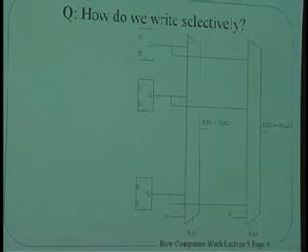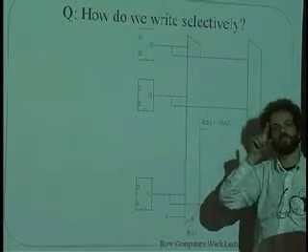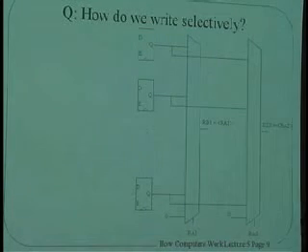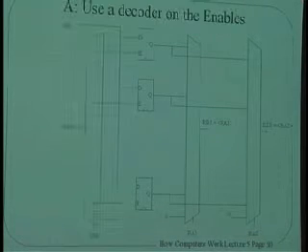In other words, I could gate the clocks. I could put a bunch of AND gates with the clocks, saying depending on which of the registers I wanted to write, I'm either going to trigger this clock or trigger this clock or trigger this clock. Change which shutter gets the finger to press on it. But it turns out, and we'll see reasons later for why this is true, that trying to gate clocks, trying to control which shutter is pressed, is actually very hard to do. And it's actually easier, and you get much more time to get the job done, to disable certain of the cameras and only enable one of them so that all the shutters are pressed at the same time, but only one of them works. And let's take a look at how that works.